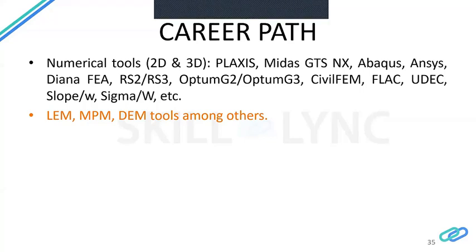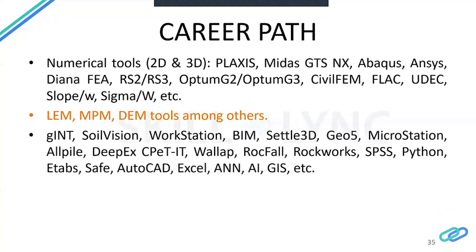For example, we know that soil is discrete and granular in nature, while in the finite element method we assume that the soil is a continuum. So this is not 100% true, and you might consider using discrete element modeling for certain cases. But for foundations, so far we are usually using finite element modeling or finite element analysis. These are other general software and general skills you have to develop with time to be a competent foundation engineer in your future career.